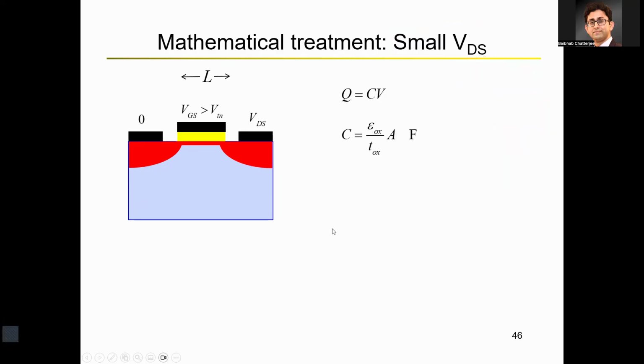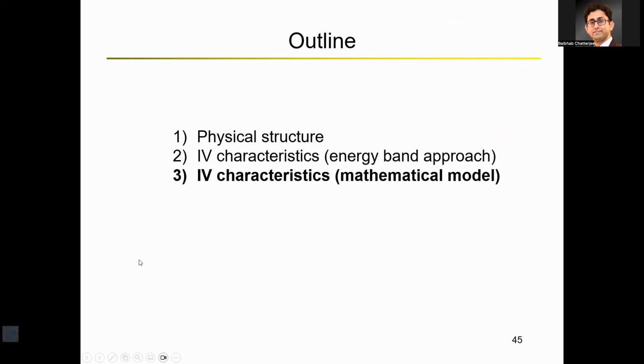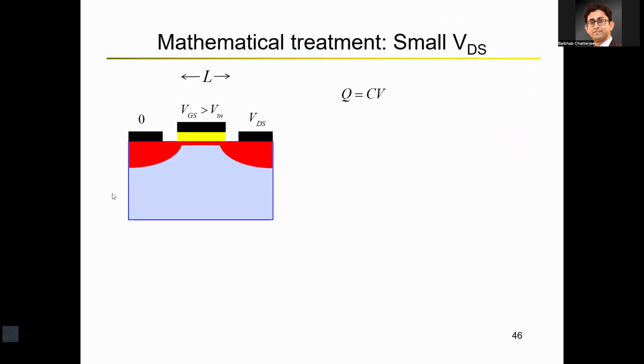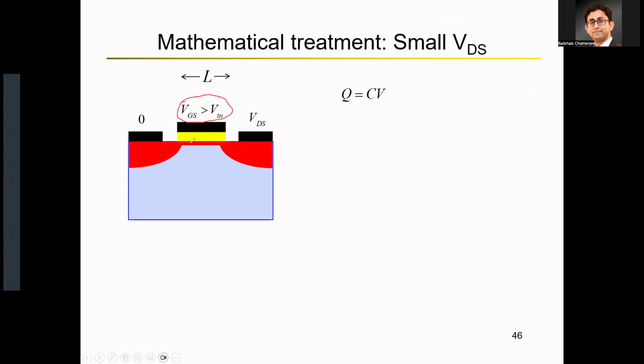That's because as you are looking at this MOSFET structure, let's say you have a gate to source voltage greater than the threshold. If you have that, you'll form a channel, right? If you did not have the gate to source voltage greater than the threshold, you do not form the channel over here. The channel is formed only if the gate to source voltage is greater than a particular amount of threshold. And that's because as this voltage is positive, you start drawing electrons from the bulk region.